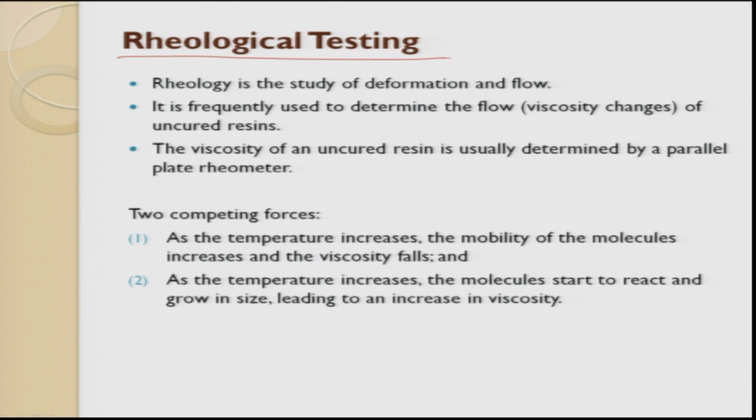Next, and the last, is rheology. Why rheology? Because the polymer is a viscoelastic material, which means the behavior changes with respect to time and temperature. Rheology is the study of deformation and flow. Deformation means shear deformation, and flow. It is frequently used for determining the flow and viscosity change in the uncured resin. There is an uncured and a cured resin. When the uncured resin is used, we try to find out the viscoelastic behavior and then start adding ingredients. So the viscosity of an uncured resin is determined by